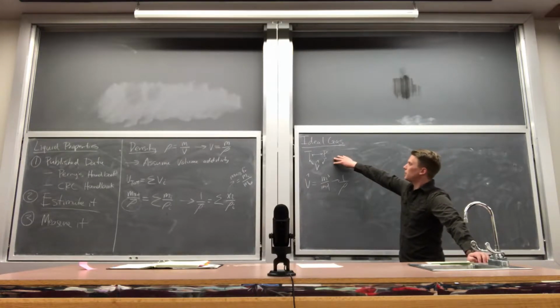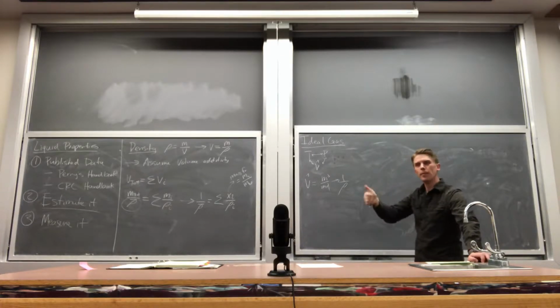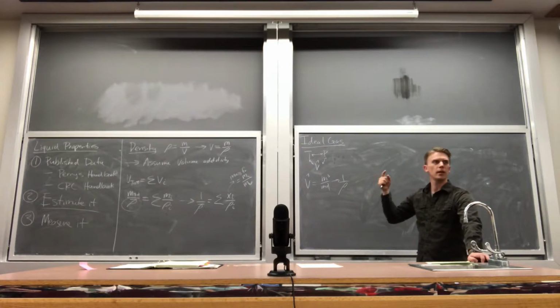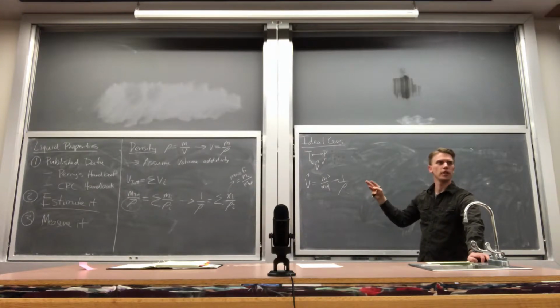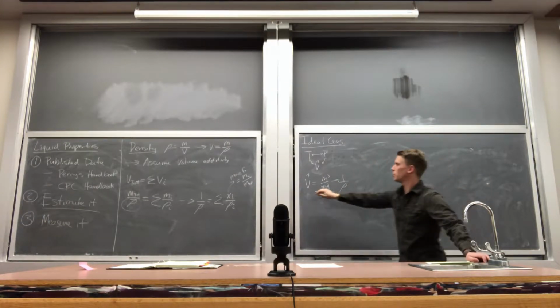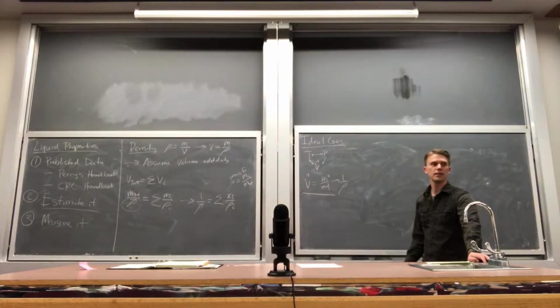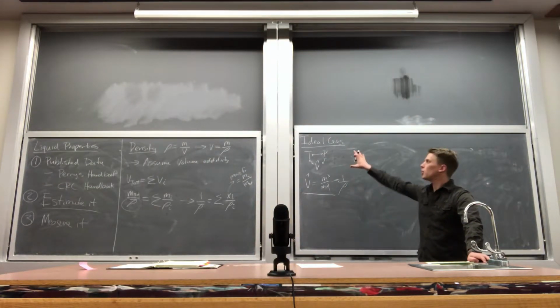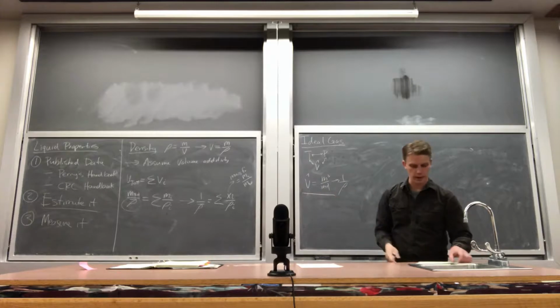So, any equation of state that relates temperature, pressure, and density or specific volume of a fluid is typically called an equation of state. Now, in Thermo 2, you'll use an equation of state to calculate absolutely everything: vapor pressure, enthalpy, entropy, Gibbs free energy. But for our purposes, we're mostly just concerned about calculating the density or the specific volume of the fluid. What we're using these for is the most basic application of an equation of state, but in reality, you can do a whole lot more with them.